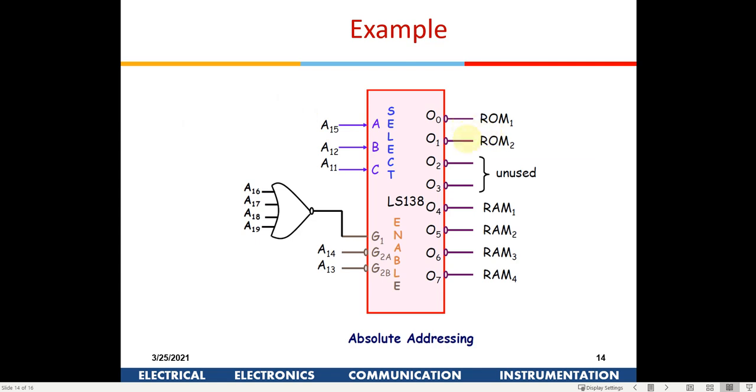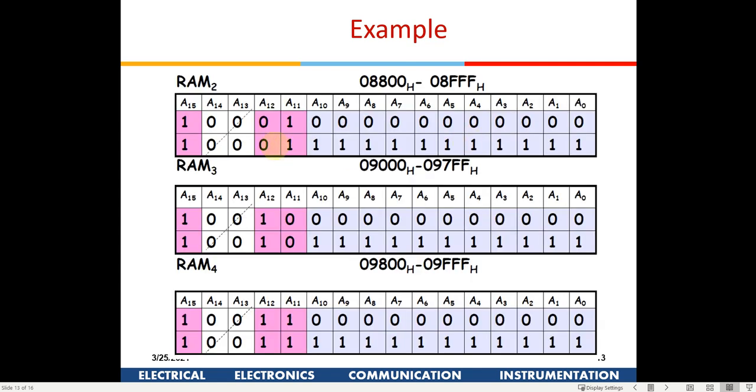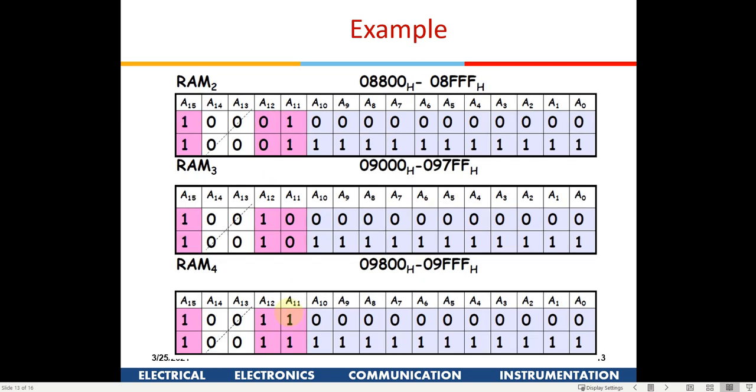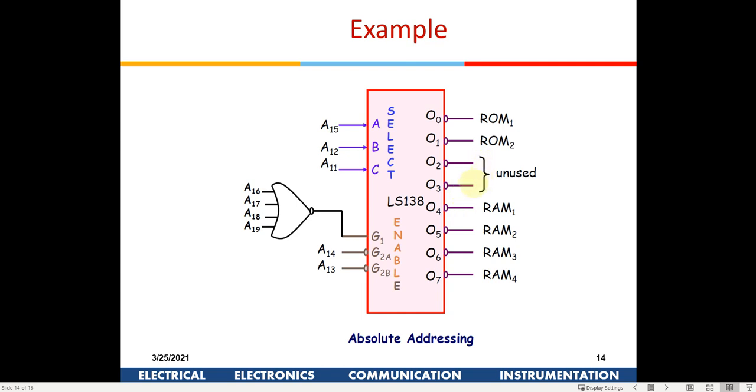And then 00 and 01. Okay, these are for the ROM. If you see, this is 00 and 01, so these are the two ROMs, and then it starts from here, right? Since these two we are not using, this is 0, 1, and then we are starting from 4. That is the reason these two are not used, and again we are starting from 4, 5, 6, 7. So these two are not used, these two are used, and here you have given A15 out here, right?